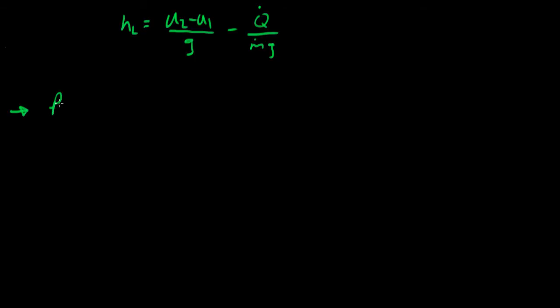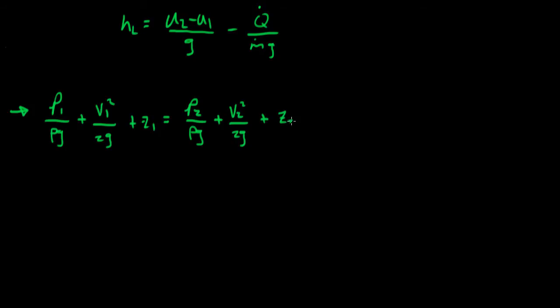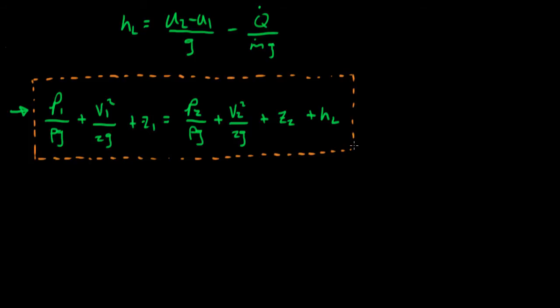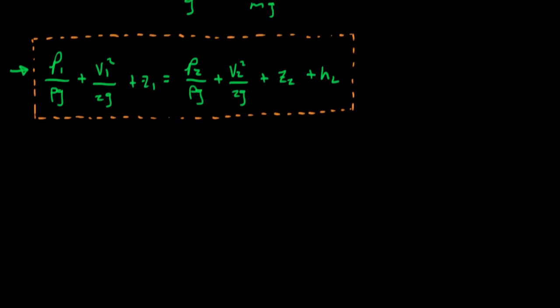One way of looking at this head loss is that it is the elevation change we would need to include between station 1 and station 2 in a frictionless flow to achieve the same result. Friction introduces a loss that must be overcome to maintain the flow. We rarely use the definition of friction head that we arrived at above. In practical applications, it is much more useful to relate the losses to the friction shear forces. These forces can be correlated for any pipe flow using the Reynolds number and the effective roughness.